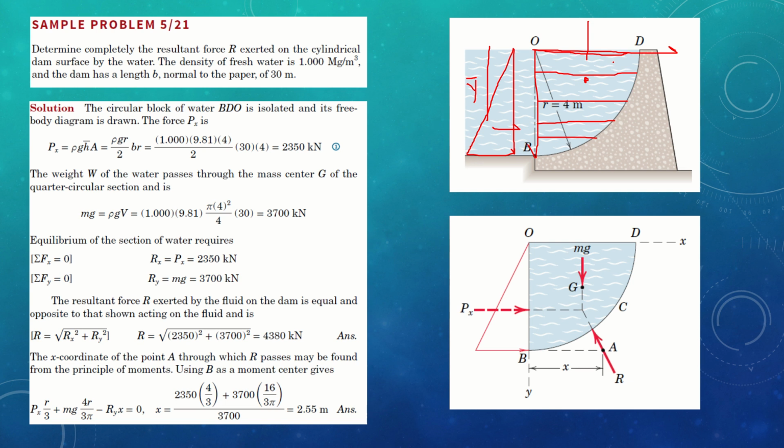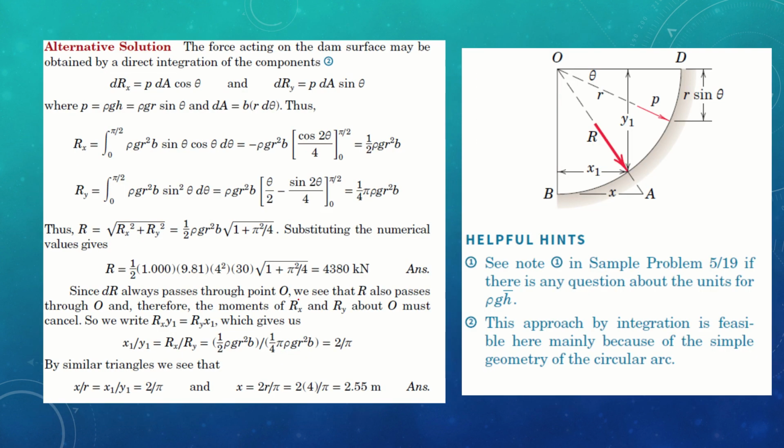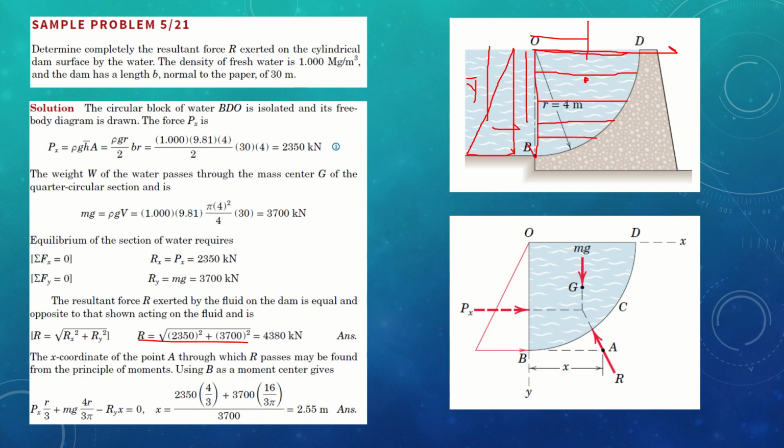What you need to know is where the center of mass exists for this particular volume. And you have found it simply through the 1/4 of circle, as you know the volume of the circle and where it exists. Based on this information, you can use the Pythagorean theorem and find the exact value where this y and this x exist, and you can find the combined reaction R. Once you have found those things, this is what is required, where exactly this force is acting.